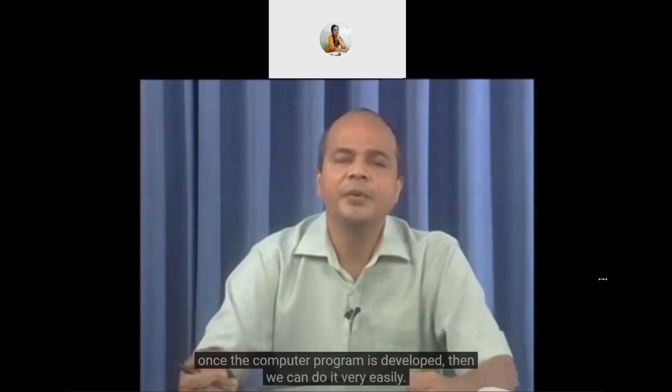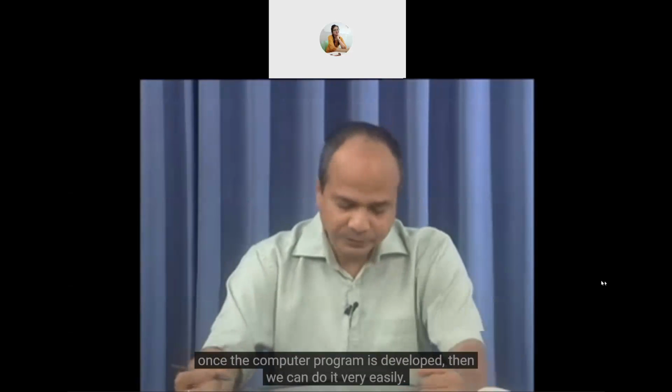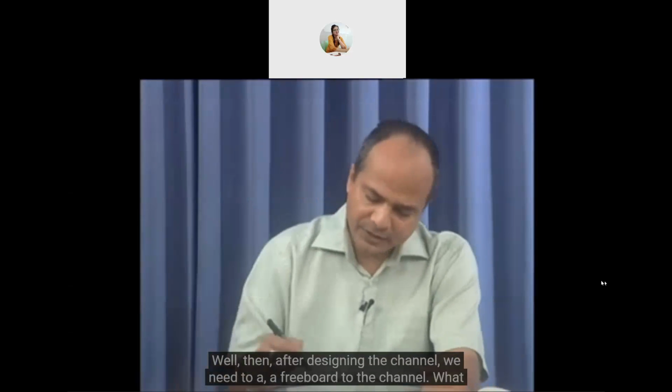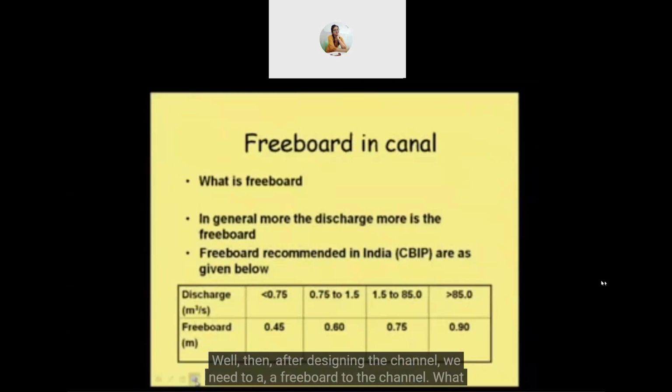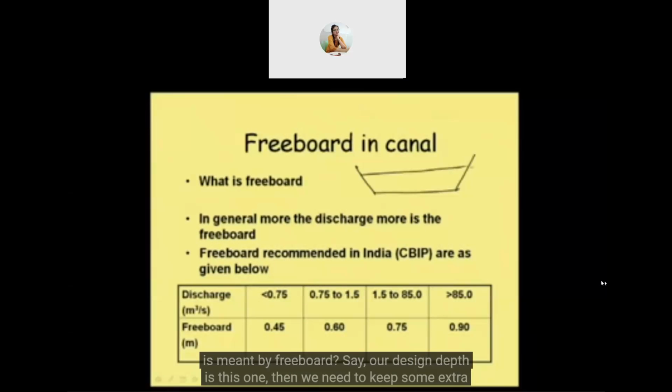Well, after designing the channel, we need to add a freeboard to the channel. What is meant by freeboard? Say our design depth is this one. Then we need to keep some extra depth over this for our safety, and that is called freeboard. So that extra depth we need to provide.